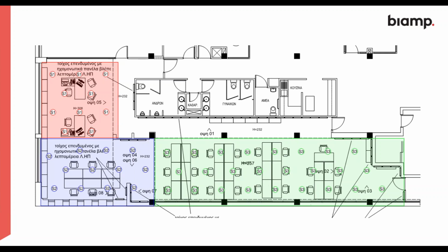A question referring back to the ceiling height that we talked about. If the ceiling is lower than 2.2 meters, it's not recommended for sound masking. We need to be cautious about the design and find out exactly why the customer wants sound masking and see whether there is another way to do it.